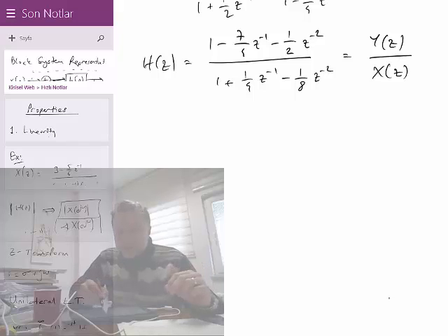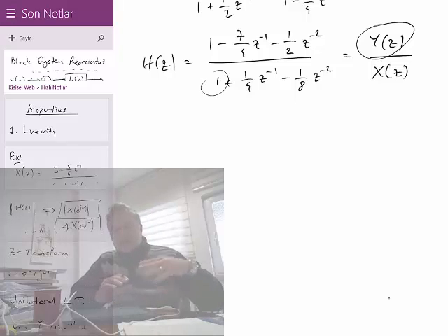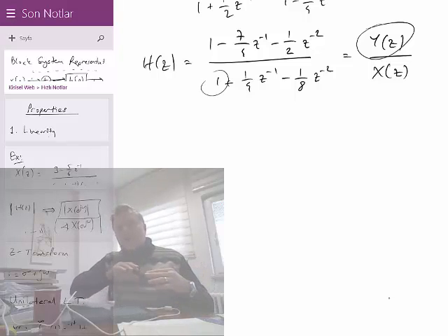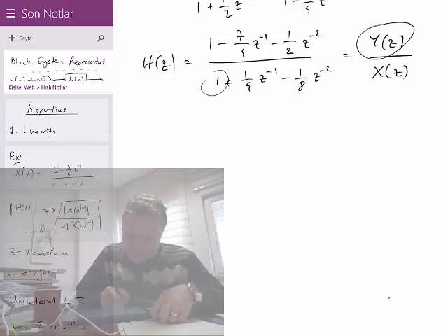And when you isolate a Y(z), this one, which is multiplied by 1 at the left hand side of the equation, all the remainders will go to the right hand side, and that will correspond to the direct form. And the direct form will be like this. X, you can say x[n] or X(z), whatever. The input comes into the picture, and there will be some feedbacks.